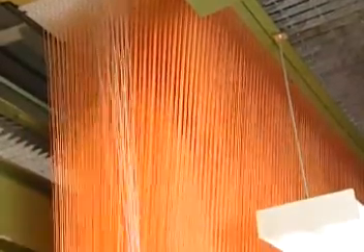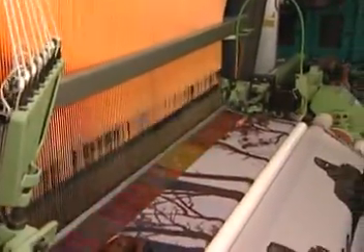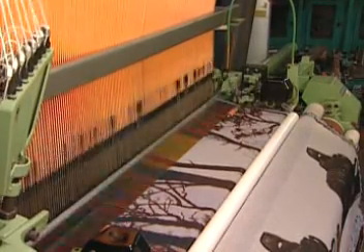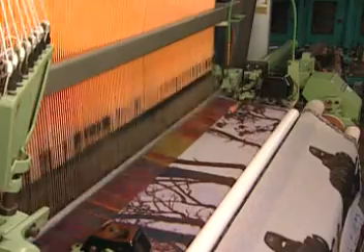Jacquard shedding exhibits control on each individual warp yarn independent of all other warp yarns. Up to 12,000 warp ends can be controlled. These systems can employ mechanical or electronic devices to actuate the warp ends. Design capability is virtually unlimited. Pattern areas can equal the width of the fabric and are almost unlimited in length.